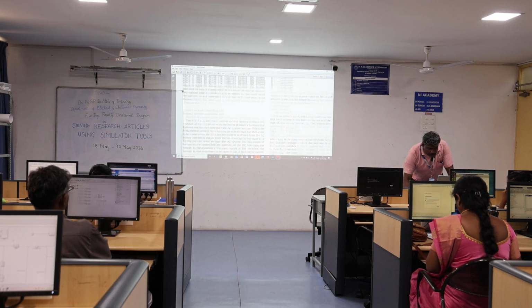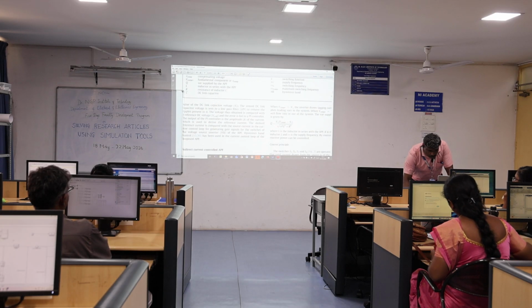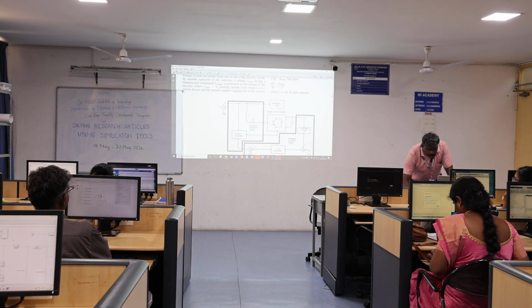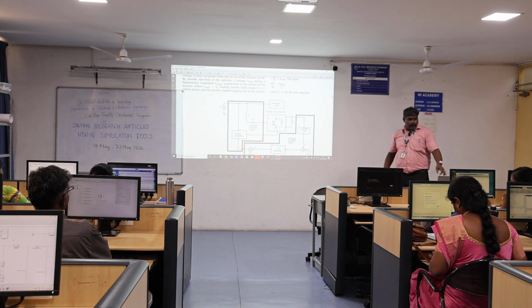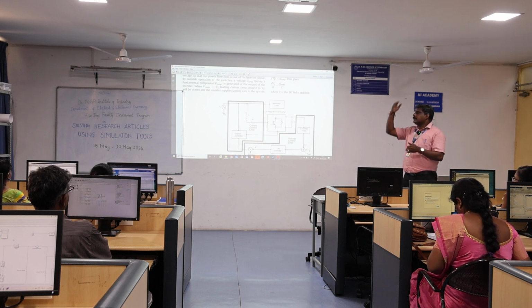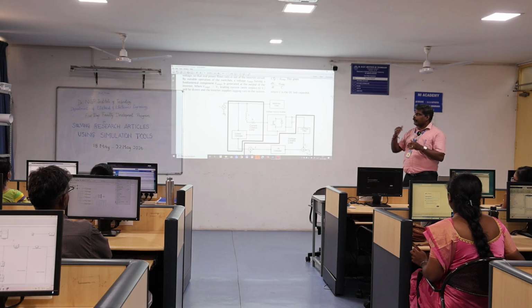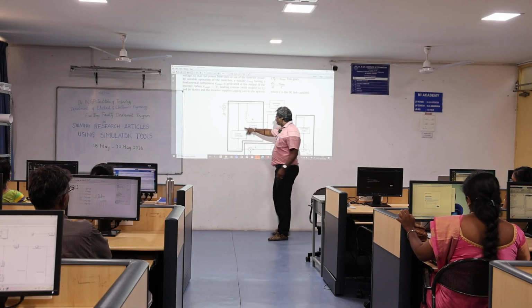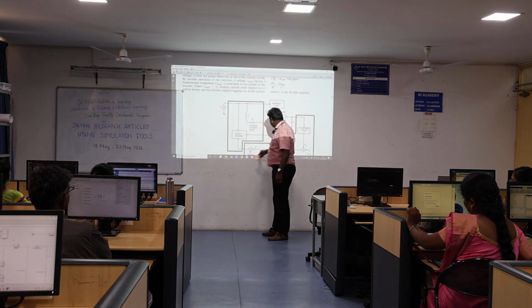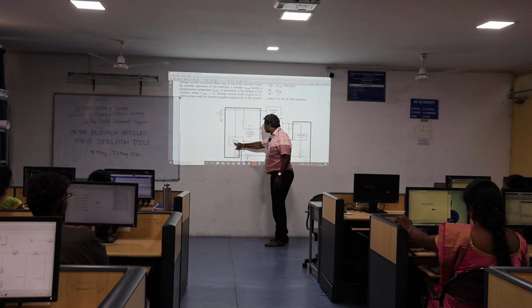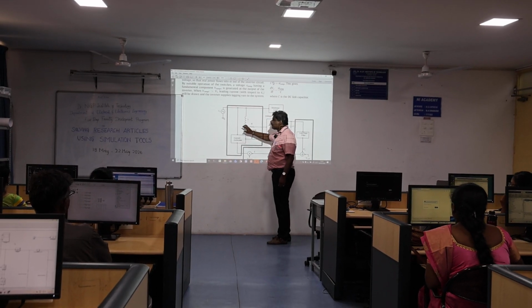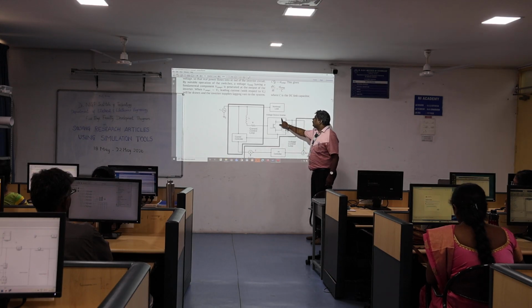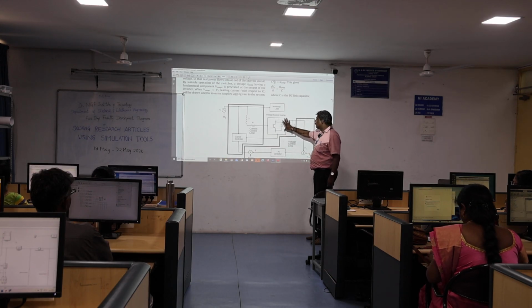So now we will move to MATLAB. Inside this current controller, I already told you, whatever I said for the hysteresis current, upper band and lower band, the reference current and measured current, this is the source current. So source current is taken from the line, and reference current is derived from our controller. Inside you have a hysteresis relay, where we can feed the band value, then we generate the pulse. The pulse is applied to the single phase voltage source inverter, which consists of 4 switches, right?